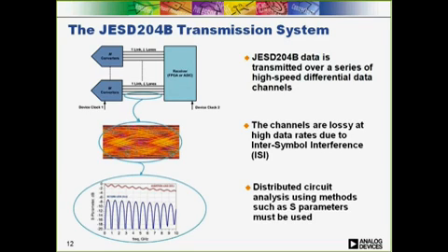Because of this increased sensitivity, distributed circuit analysis methods for modeling the transmission line should be used since a lumped model is not adequate. This illustration shows an example of what insertion loss and return loss from a network analyzer looks like using analysis software.